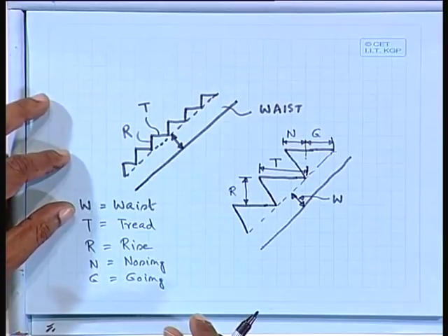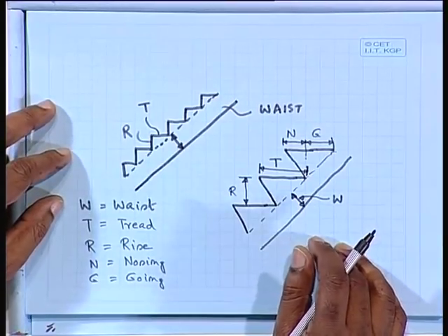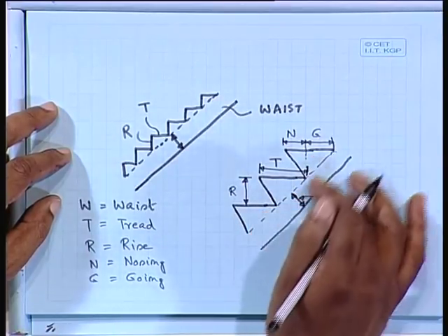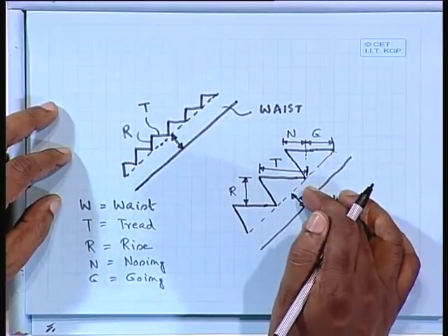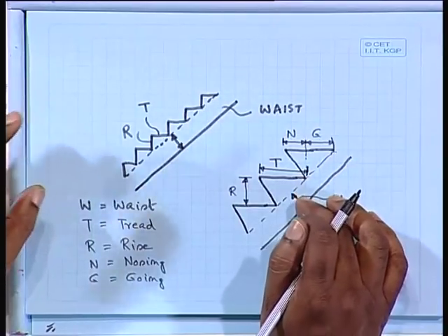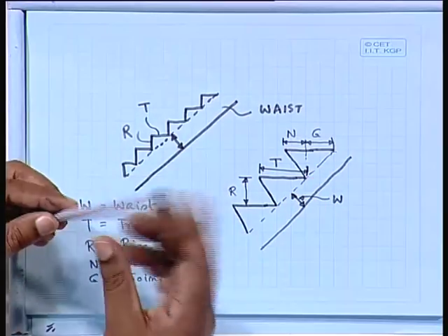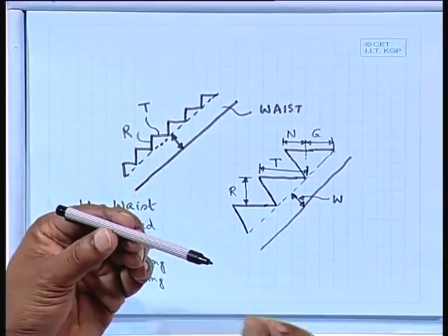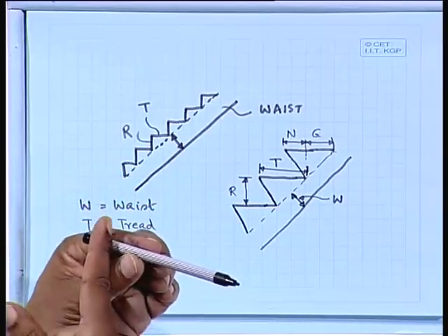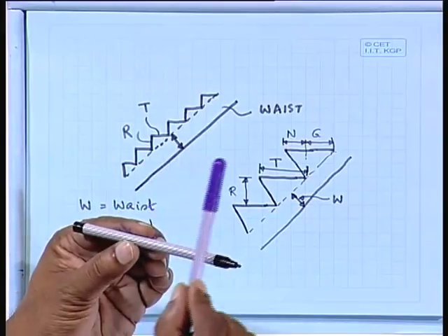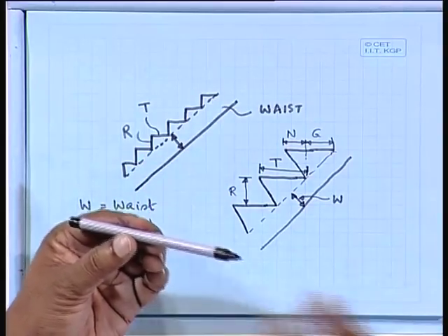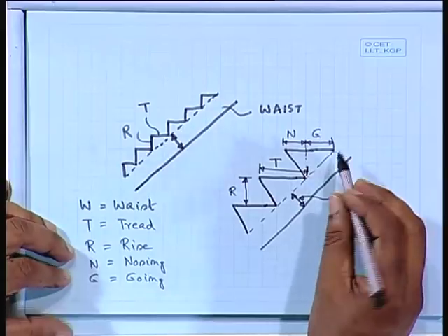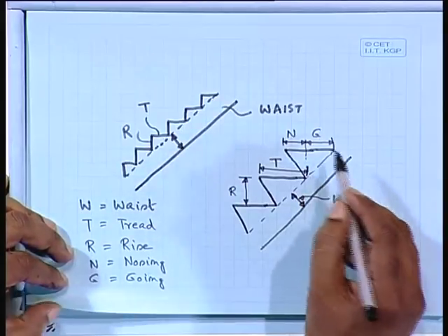So, what we are assuming here in this case, we shall take the dead load of these steps, but all the things will be supported by this waist slab. This is the most common one. The other case is that you may have a beam like this, and over it are the steps, like this. That is possible, the one I have shown you. But that design will be different compared to this one. This is the most common, popular one. So, let us see how to design this one.